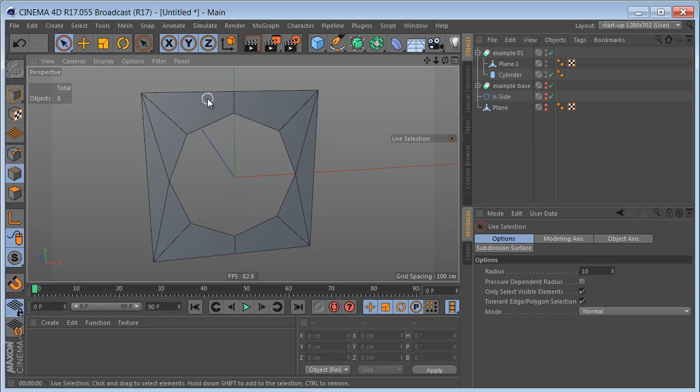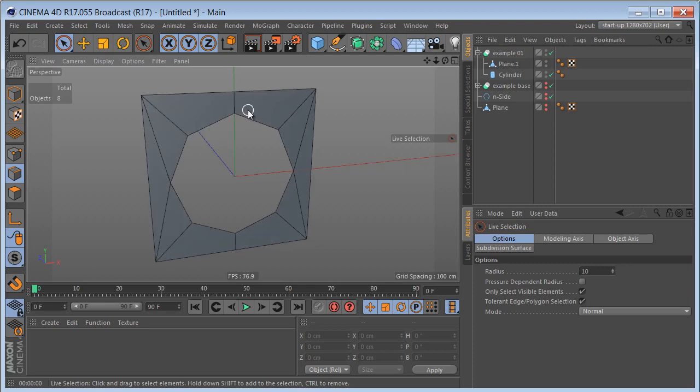And that's important because we're going to wrap this around a circle spline later, and we're going to use subdivision surfaces. So we need to make sure that the segments along the height stay even, because otherwise subdividing the object will not give us the result that we want. And maybe I'll just show you an example.